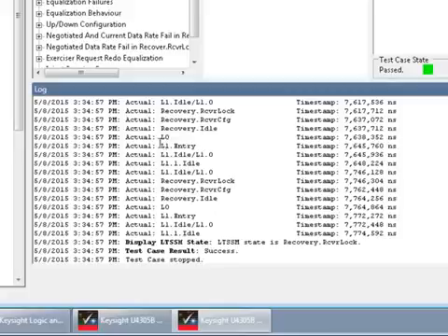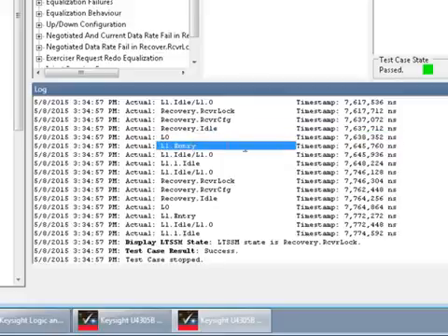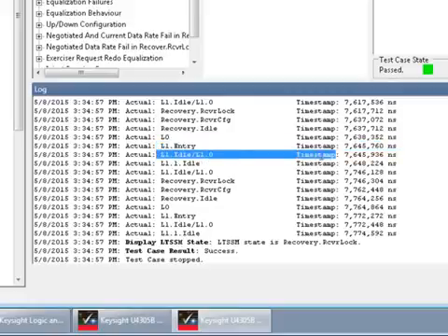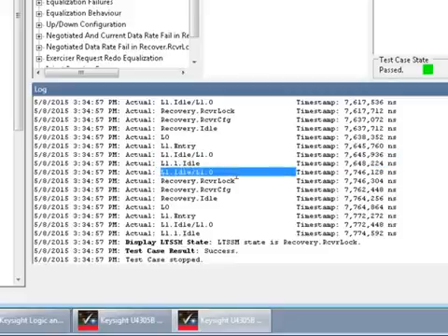So over that time, what we see is a timestamp for each event. It was in L0 state at this timestamp, entered into L1 just a few microseconds later, 10 microseconds later, went into L1.0 idle, went into L1.1. That took about 3 microseconds to get into L1.1 idle. Then here it's coming back out, and you can see the time difference there was about 100 microseconds.